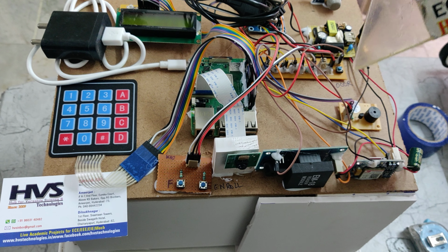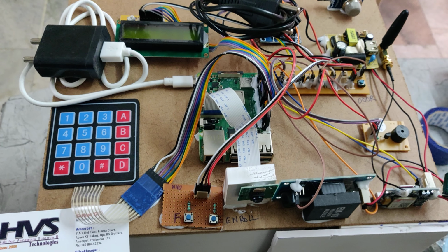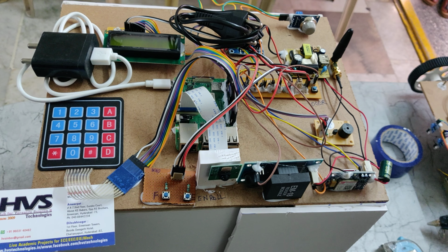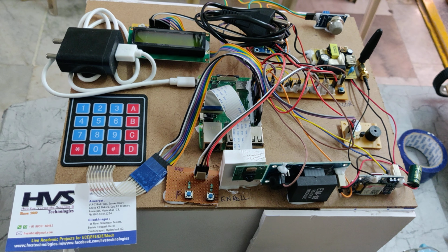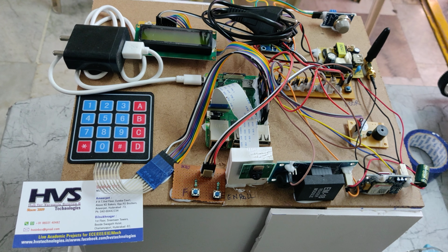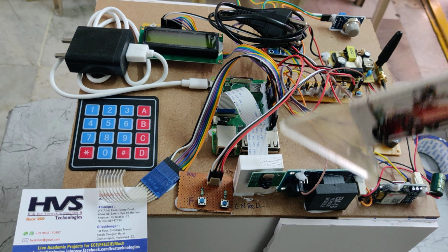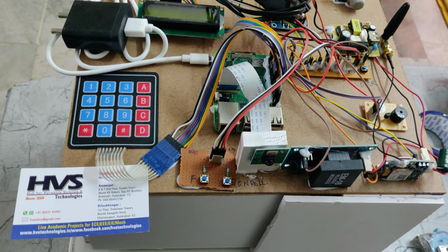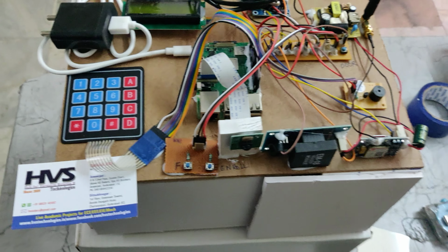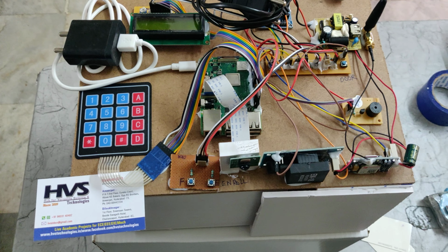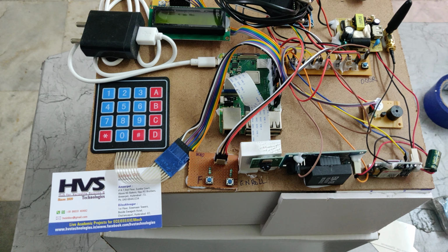If a person is trying to access this chamber, he or she has to show the RFID tag near the RFID reader. After showing the RFID tag, the system will check the oxygen levels, meaning gas levels, inside this chamber. If it is normal, then the system will capture the photo using this Pi camera, and if the face is recognized properly, it will send a message to the registered phone number. That message consists of a randomly generated OTP, and by entering the same OTP from this keypad, the system will control the door in opening and closing.